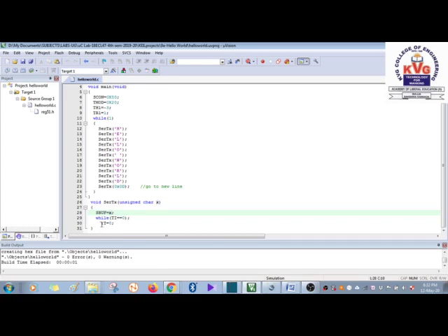Then come out of the loop and make TI equal to 0 so that you can transmit the second character, that is E. So after that it gets out and it comes here to the second one. So E, you call the function and send E. So E comes here, it goes and sits in SBUF, and when the transmission is finished, TI becomes 1, get out, make TI 0, go back. And then the same thing happens to L. Call the function with L, L comes here, L goes and sits in SBUF. After transmission, TI becomes 1. So this goes on and on until it comes to the end here.